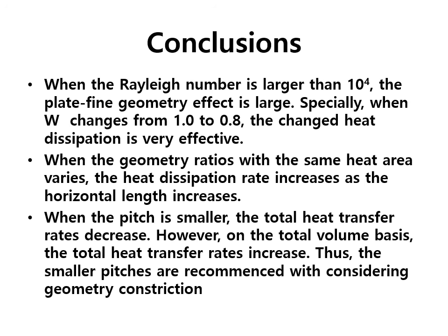And the conclusion: when the Rayleigh number is larger than 10 to the 4th, the plate fin geometry effect is large, especially when W changes from 1.0 to 0.8. The change in the heat dissipation is very effective.